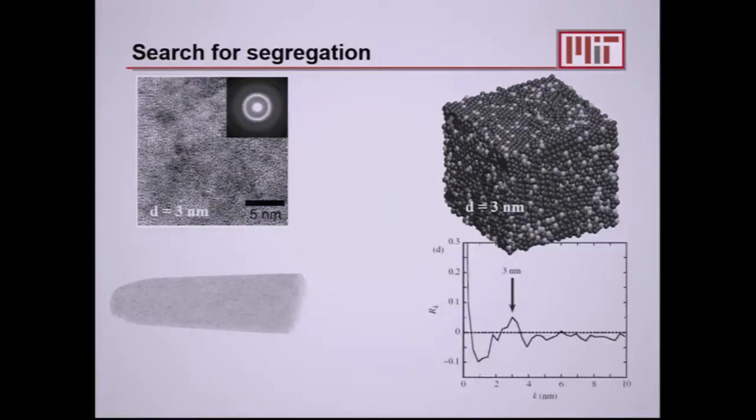For example, one of the things you can do is look at the two-body correlation, the pair correlation function between tungsten atoms, right? If all the tungsten atoms are preferentially distributed on the outside of the grains, you will see something like this, where there is a primary maximum that is at the grain size. That's, if you will, the wavelength of tungsten in the specimen, and it matches the grain size. And we know that's because, indeed, in the simulation, it is segregated at the boundaries.